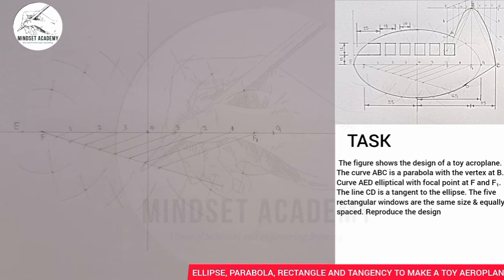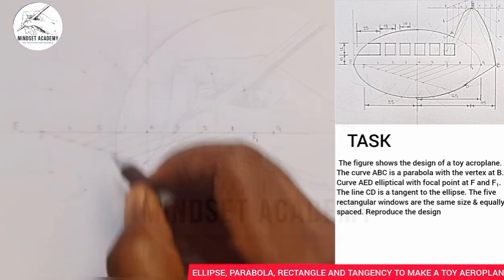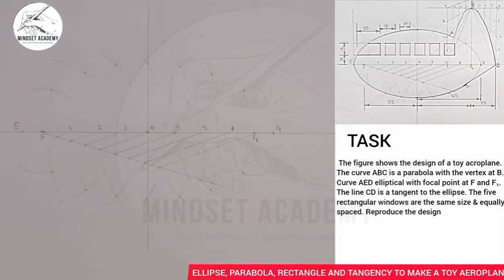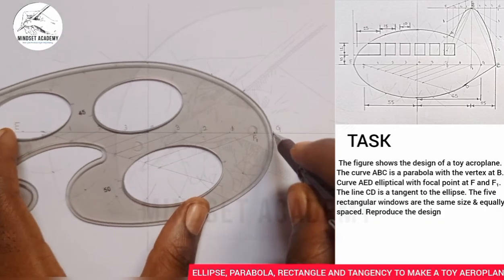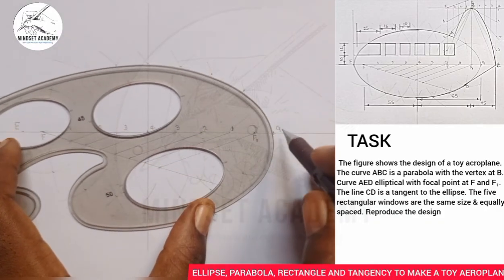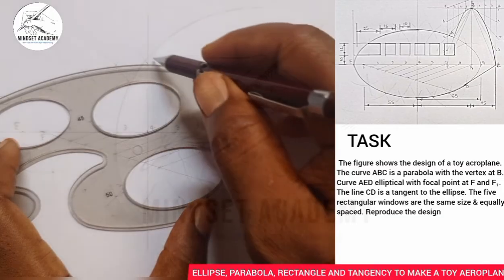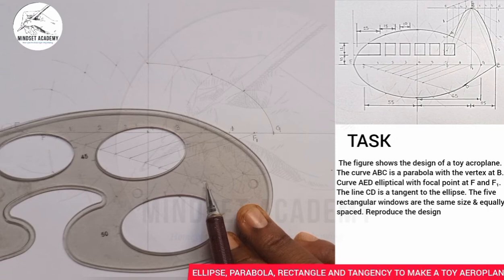So this is where they are all marked. These are the points I am going to join together using my French curve. Now I'll join these points using faint lines first of all, right? I will not complete it yet. You see all these points targeting G and this point here, the horizontal and the vertical. I'll have something like this. Faint line first. Can you see that?